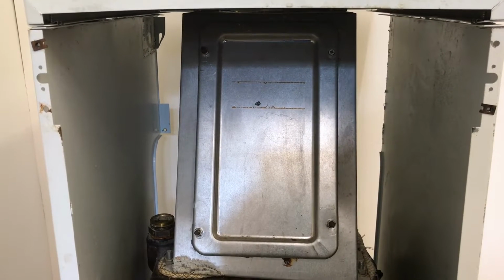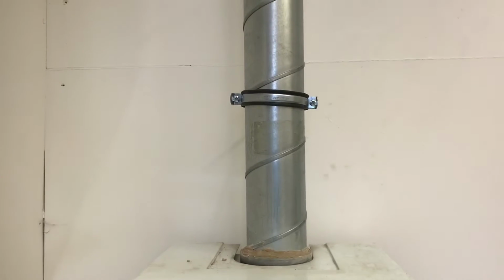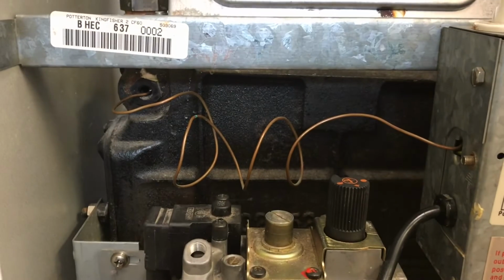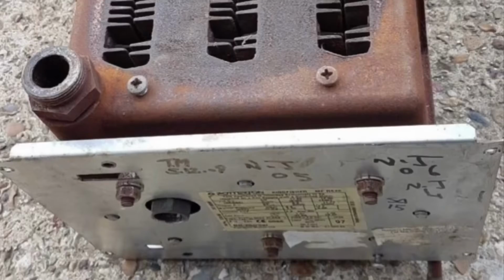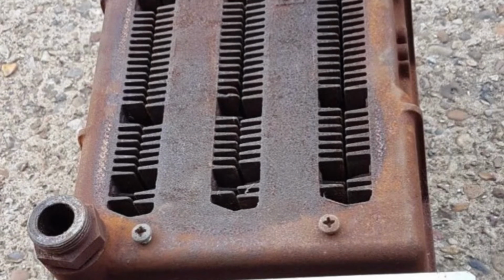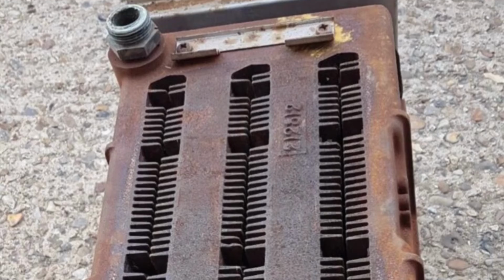We have the primary flue, we have the draft diverter, and we have the secondary flue, and at the end of the secondary flue we would have the terminal. In the middle, the dark bit you can see, is the cast iron heat exchanger. Cast iron heat transfer is lower than that of stainless steel or aluminium heat exchangers, making them less efficient.